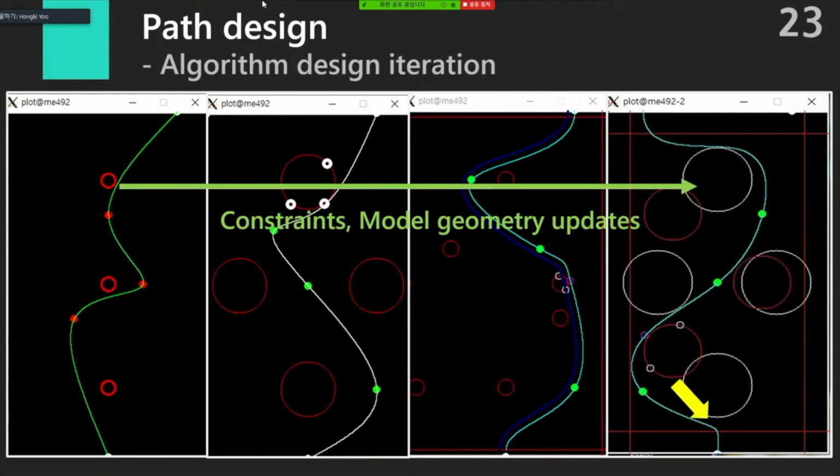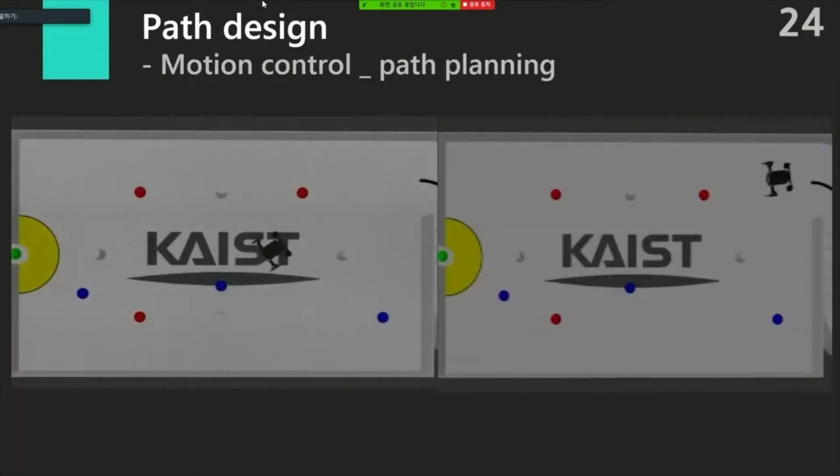And right here, this is why we use a clamped B-spline curve. So we can go perpendicularly into the goal zone and then do the vibration motion. So please focus on the path planning. We get the balls, then slowly go to the goal point.